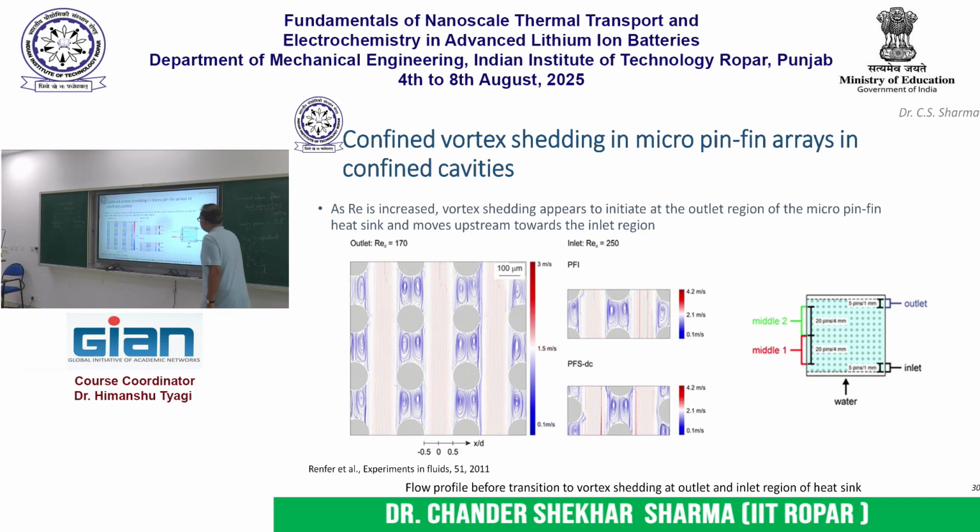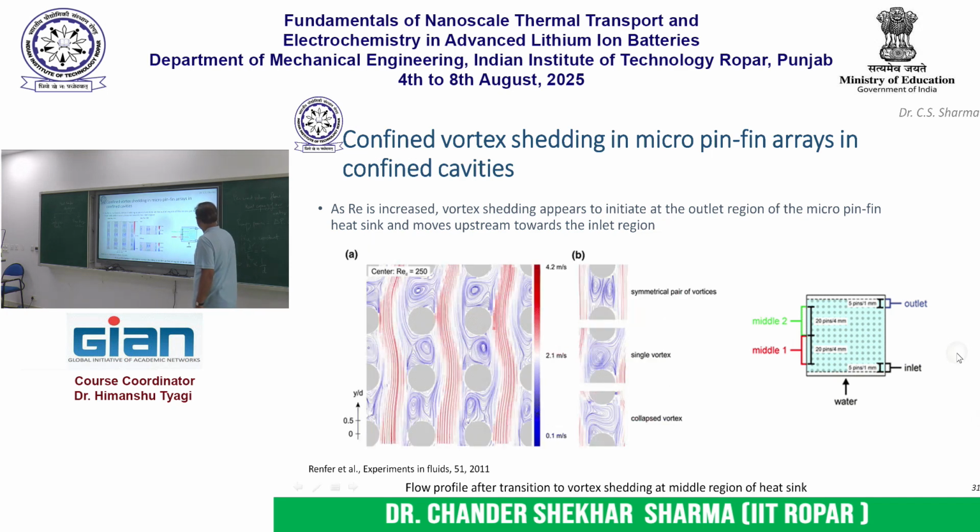Okay, but as you increase the flow these recirculation zones become unstable and they start to oscillate like this, and they start to disturb this flow also, and that leads to a continuous vortex shedding, and that improves the heat transfer.